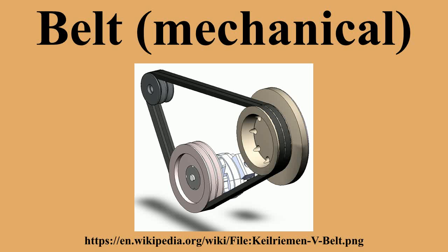When the top section of a belt is in resonance, the vibration of the machine is increased. However, an increase in the machine vibration is not significant when only the bottom section of the belt is in resonance. The vibration spectrum has the tendency to move to higher frequencies as the tension force of the belt is increased. Belt dressing. Belt slippage can be addressed in several ways.